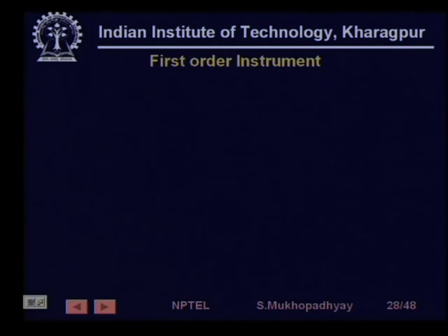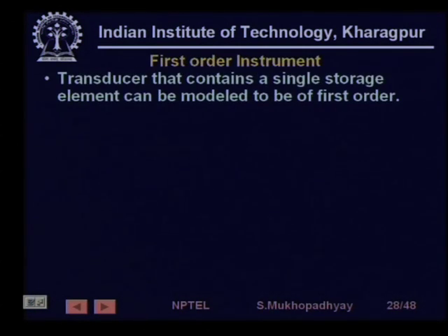On the other hand, there are some kinds of instruments where if the input changes suddenly, the output cannot change suddenly, the output takes some time to rise. For example, let us take temperature measuring instruments, for example, a thermocouple. Wherever it is making the measurement of the temperature, maybe it is steam, then the bare thermocouple is actually not inserted into the steam, because that will damage the sensor, it will degrade fast. So, it is actually put inside a tube.